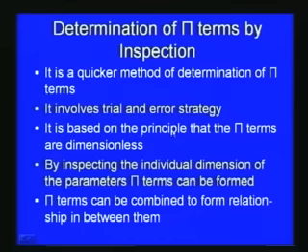Once we decide the repeating variables and the fundamental dimensions, and then inspect the particular problem, through inspection or trial and error we can decide how the pi terms are formed, or which way we can combine each pi term.